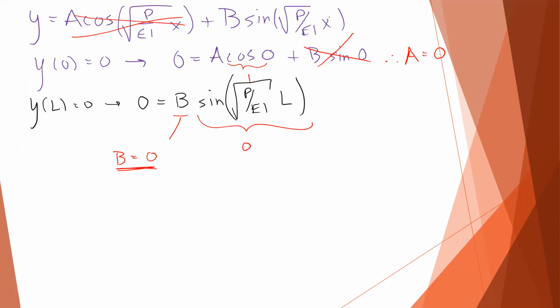What would it look like? It would look just like a normal column, just sitting there. You wouldn't know it. Now, it's extremely difficult for this to actually happen because everything has to be perfectly aligned, but that's part of what makes it so dangerous, that it looks fine. You can't tell that it's reached that load. The only way you tell is you see it deform laterally.